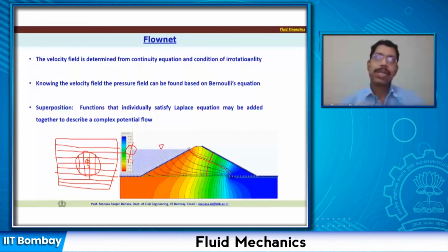It means that, we know that property, the discharge between two streamlines is the difference between the values obtained for the streamlines, let us say psi1 and psi2. Okay, so psi1 minus psi2 or psi2 minus psi1 is going to be constant all through.